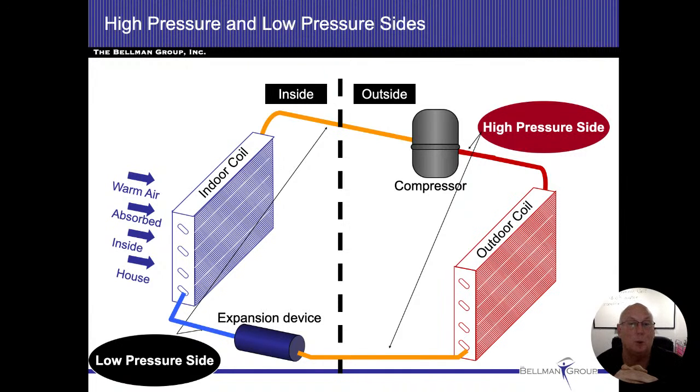And then from the outdoor coil, as it leaves that coil, including the expansion device or the metering device, until it gets into the indoor coil, that's where it's all going to be a liquid. The only places that we're supposed to be changing state is going to be in those coils. All right. So I'm expecting you to know when it's high pressure gas, when it's high temperature gas, when it's high pressure liquid, when it's medium temperature high pressure liquid, and then after the expansion valve, we're going to be low temperature, low pressure liquid.